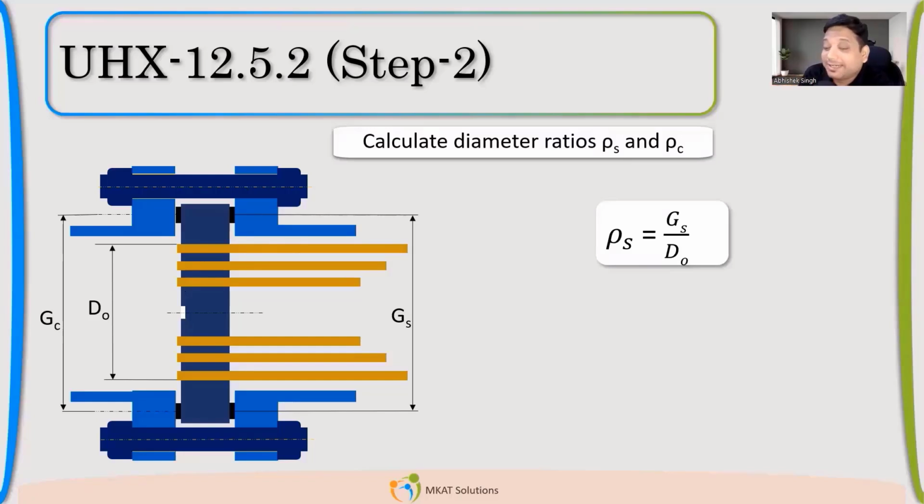Because of bolts, the gasket reactions will be acting on the tube sheet, and that is the GS. Because basically for your tube sheet, the load apart from pressure load will be because of bolts also. And in the sandwiched case, it is getting transferred through the gasket.